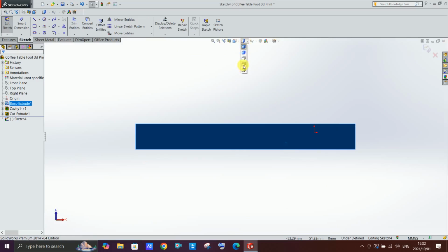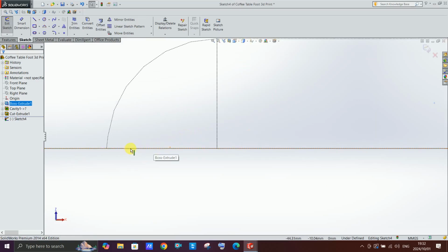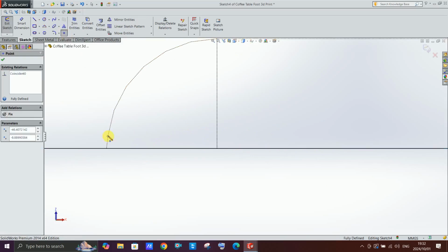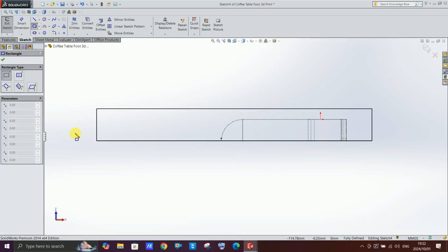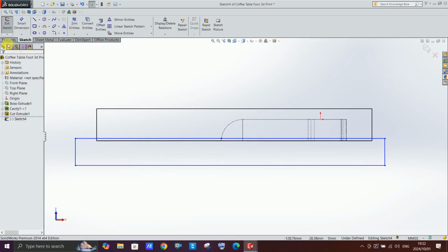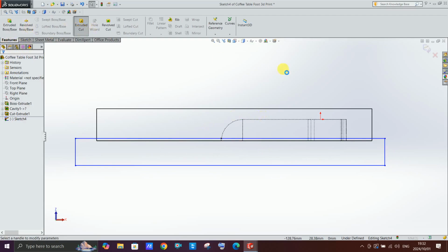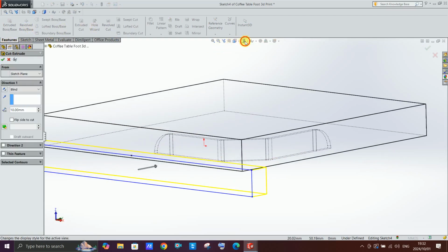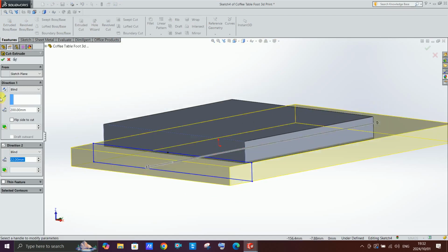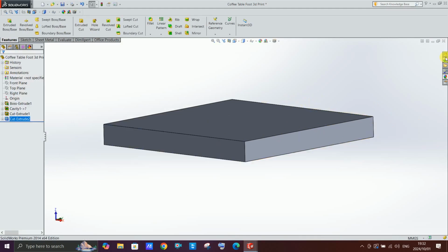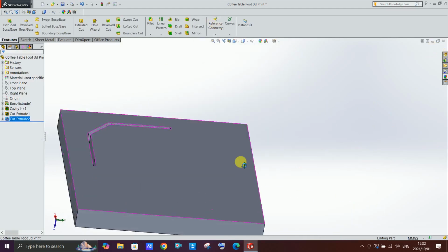I want to see through the thing. So it's basically from there. I'm just going to put a point there. Okay. I'm gonna drag a block now. I'm gonna make it a little bit shorter. I'm gonna extrude cut. You can see everything again. Boom. Okay, so it's shorter now. So I won't have that issue.